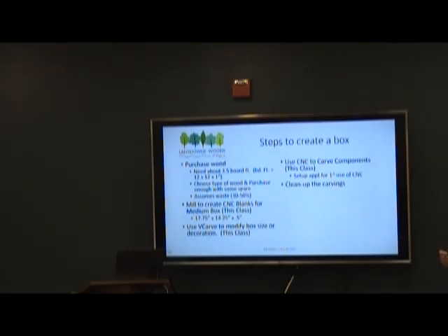At some point after the cut, it's the cleanup work. How to go about successfully breaking the components out of the blank, cutting away the tabs, using sandpaper, chisels, and maybe a couple of machines to clean up the part to where you can use it. And then stepping forward, getting a 1/2-inch piece of wood that you can use as the bottom.